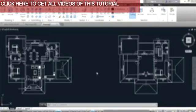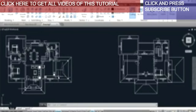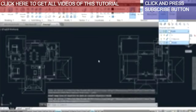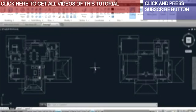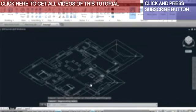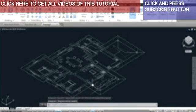We will be using this plan only as a reference while you create 3D objects. That means we should not create any of these objects in the plan layer when you make 3D models. So we will go to the plan layer and I'll just lock this layer. As you know, when you lock a layer, you won't select the objects in that layer under any circumstances by mistake. So I'll switch over to the isometric view. Okay, so this is the right point to start our 3D work.